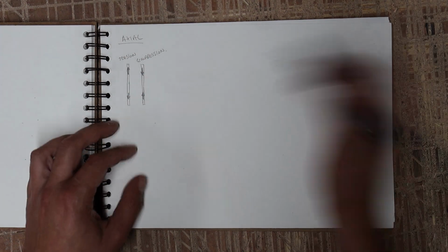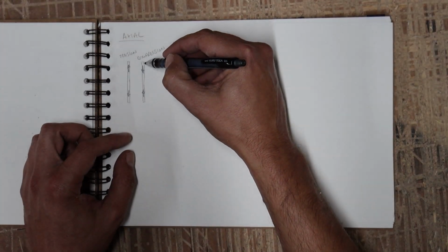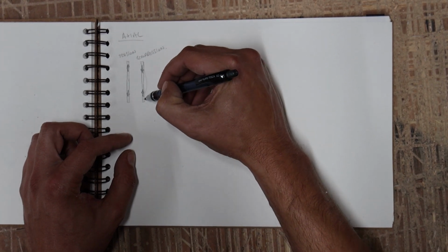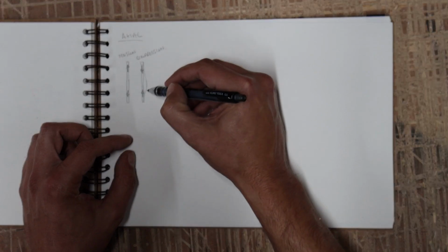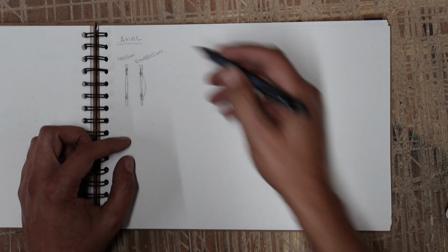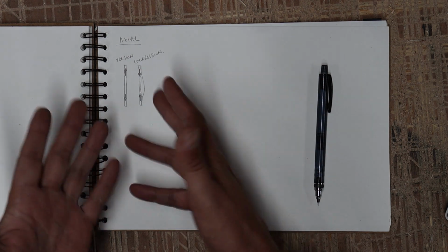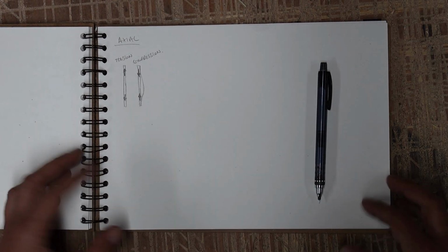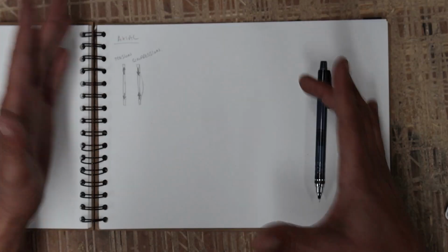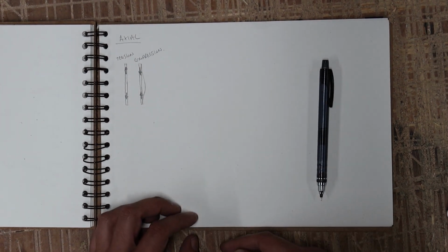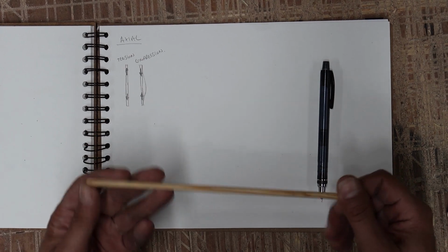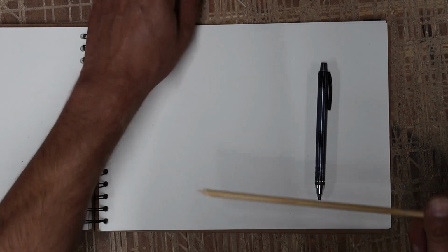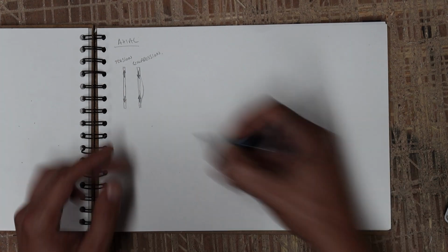I'm hoping that buckling is something you're probably aware of. When you compress something, its natural reaction is to want to bend outwards. And this is a really difficult mode of failure to analyse because it doesn't have much to do with the material that it's made of. It's more to do with the shape and geometry of the section that's being used. The fundamental strength of it obviously does come into action because it snaps. It doesn't yield the way that a tension member does, but it's different.